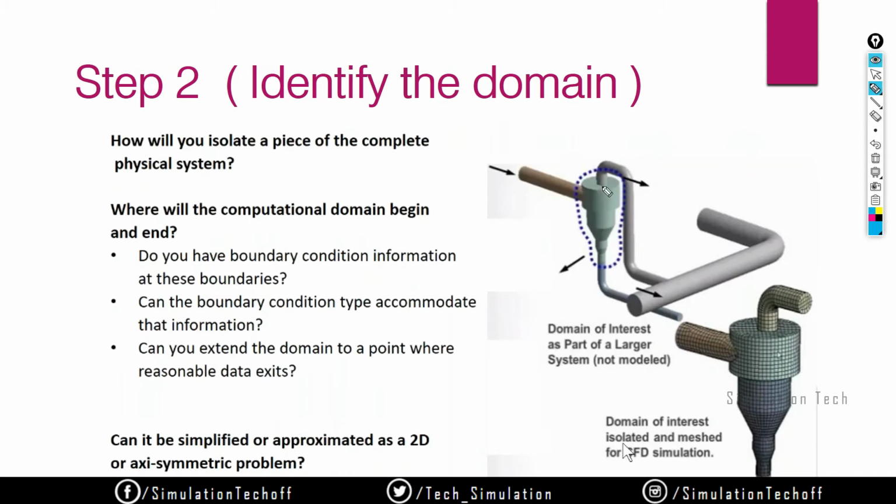So why is that? Because if you assume the initial velocity of the liquid, the liquid flows from this end to this end, right? So when I cut this model here, the velocity of the liquid at this end will be exactly equal to this end. For example, if it's 5 meters per second, it doesn't change over here; it similarly has the value of 5 meters per second from here itself. So I can cut the model and delete this. You don't need to include that. You can start from here itself, because the analysis actually takes place from here. So it's a very important thing.